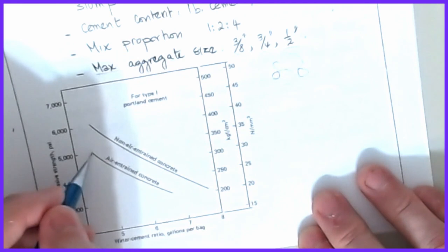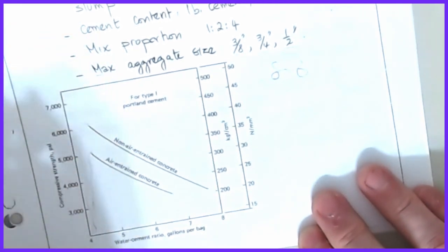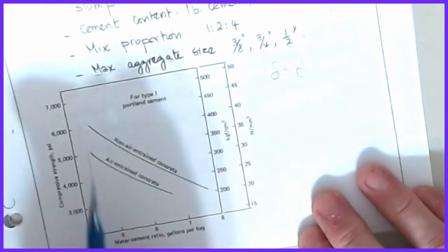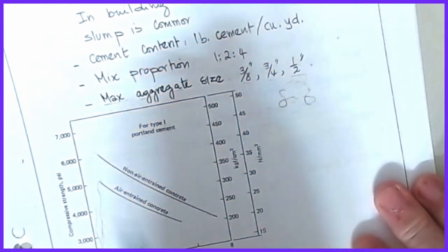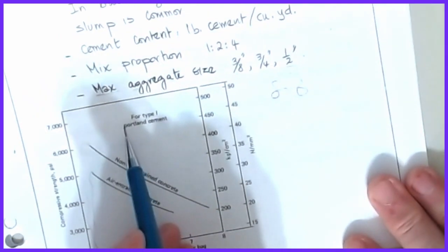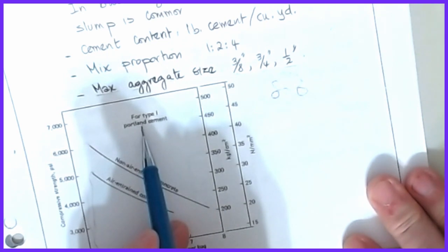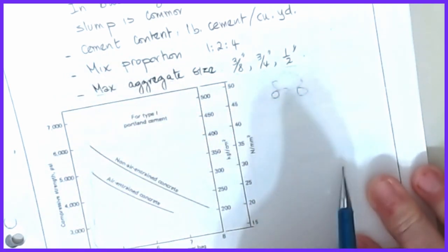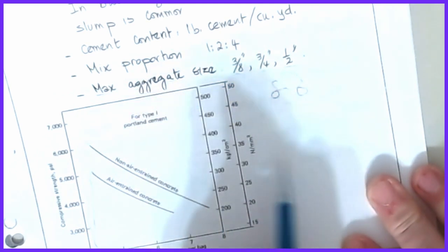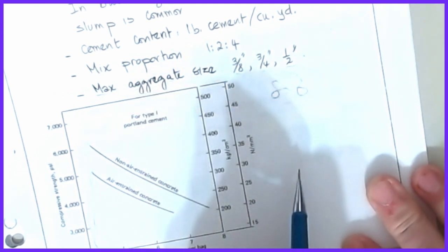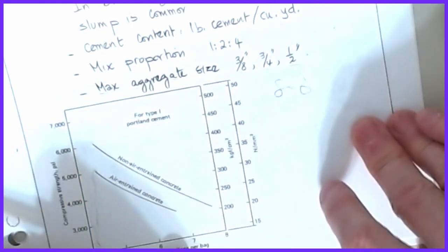Now, again, this curve falls off very fast back to zero when I don't put any water into things. So there is an optimum point. There are different types of cement that have different characteristics. This is what we call a type 1 Portland cement, which is probably the most common. But you can also do type 3 cements, which give you higher early strengths for the same f'c, and that's often used in the precast industry. So depending on your application, the type of cement is an issue.